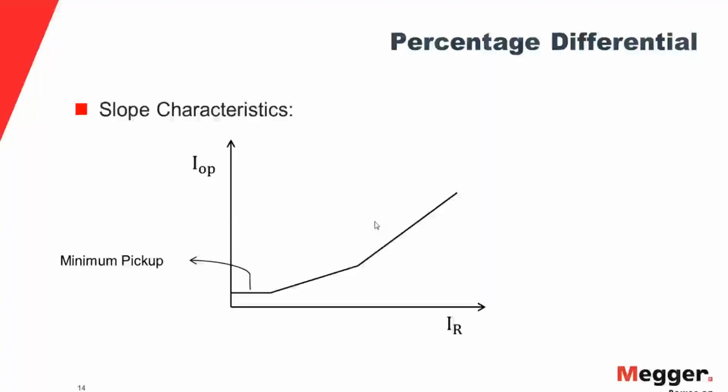So the DC component is going to be a DC offset of the AC waveform during the inrush on the transformer, and that's going to die out pretty fast as the flux builds up in the core of the transformer. That DC component will die out over time. I hope that answers his question.